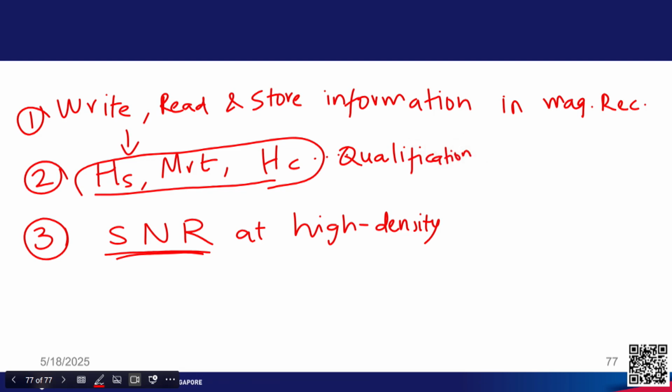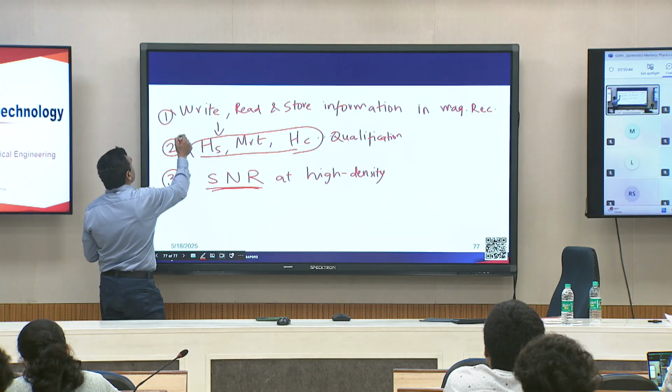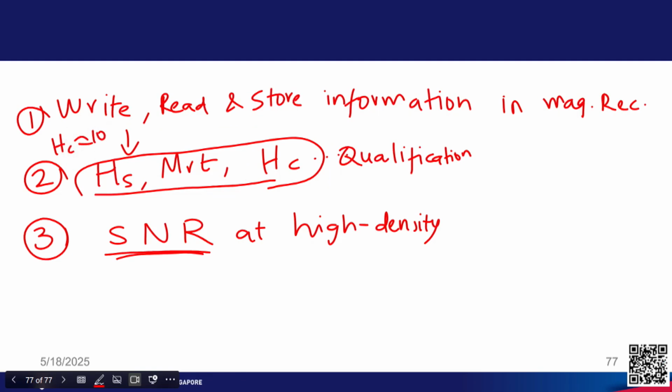To give you some example, I see many papers on magnetism. People will study some magnetic material which may have a coercivity of maybe 10 Oersted, but still they will write in the introduction that magnetic materials are useful for magnetic recording and all those things. Okay. So, when a material has 10 Oersted coercivity, you cannot write that kind of introduction, because 10 Oersted coercivity is totally useless for magnetic recording. Okay. So, we are talking about materials having 6,000 or 10,000 coercivity.